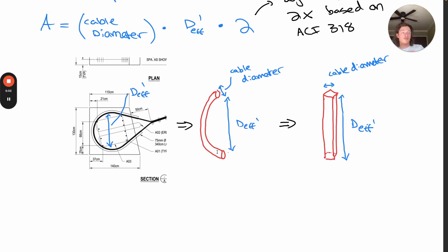So once you have all of your information about your bridge input into your design tool, you can adjust that variable t and figure out, okay, we need 3 days or 4 days or 7 days before we can officially begin hoisting our cables, or we can officially begin decking in order to avoid any early failures.